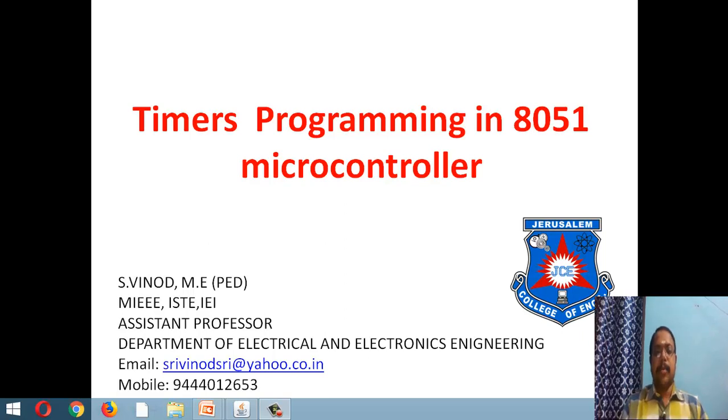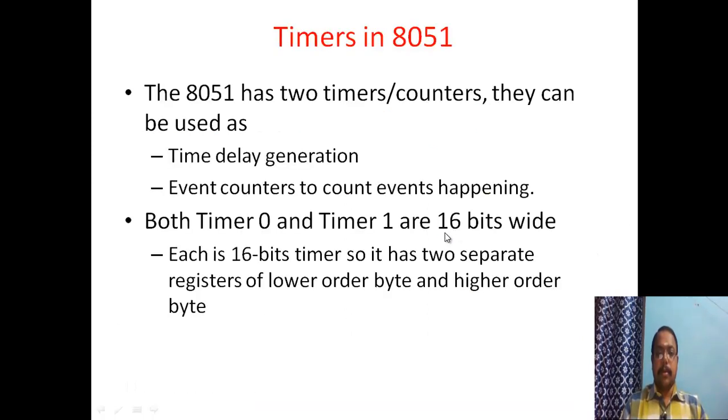Let's today discuss timers and how to do programming in the 8051 microcontroller. In 8051 we have two timers, timer 0 and timer 1. A timer can be operated even as a counter. There is a small difference between a timer and a counter.